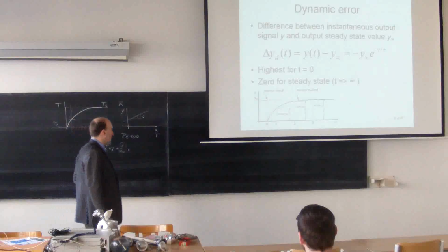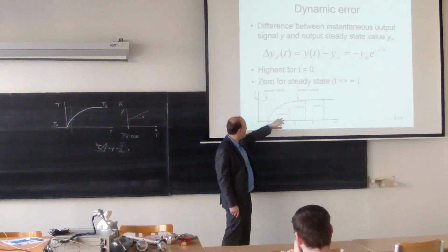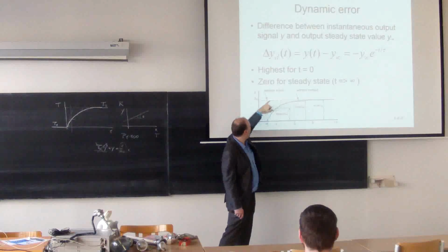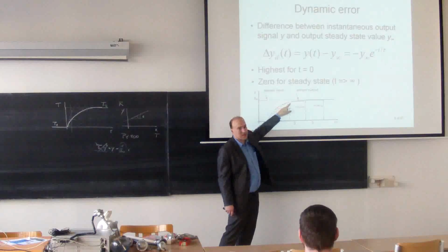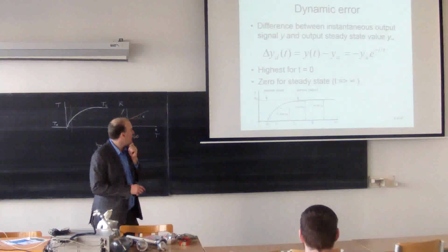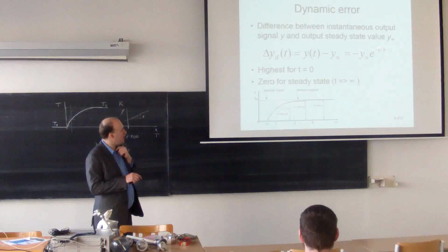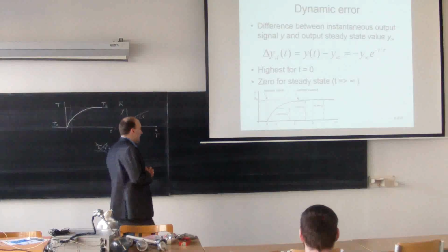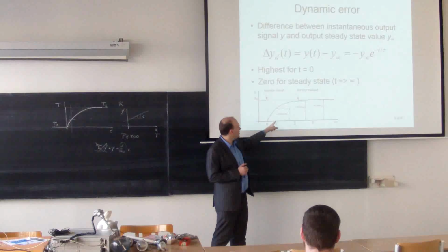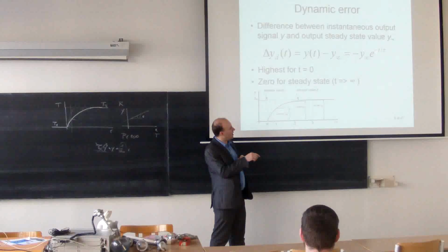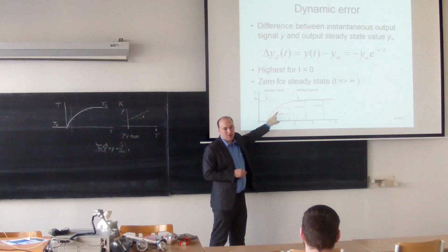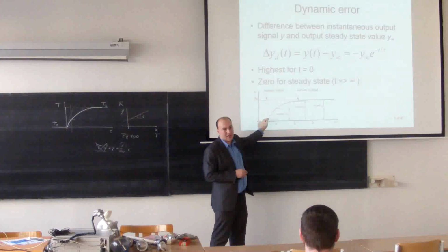So if you look at this picture, here there is a transient response. Sensor input is this curve, sensor output is this exponential. If you analyze the equation describing dynamic error, you can find out that if I wait one time constant, you will be only within about 63% of the new steady state value.